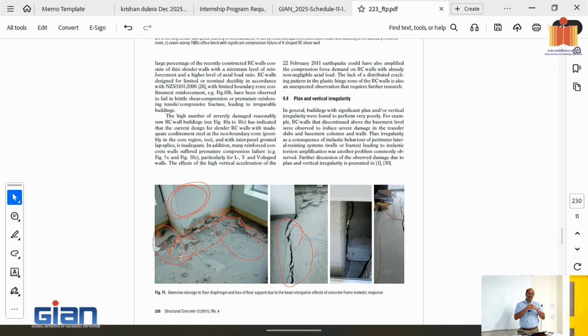So typically when beams and floor slabs are attached to the column, this plastification will elongate the members. If the beams are elongating, that elongation has to be accommodated by the floors themselves. Typically we ignore them, but it is something that people have to account for. So one of the big pushes in the US was, when they see this gap opening up, they will say, how are the floors going to accommodate?